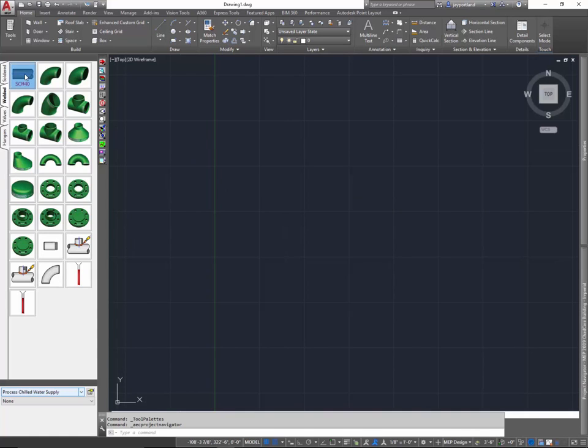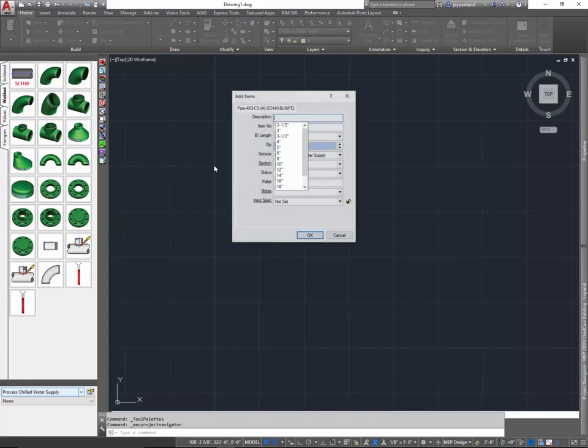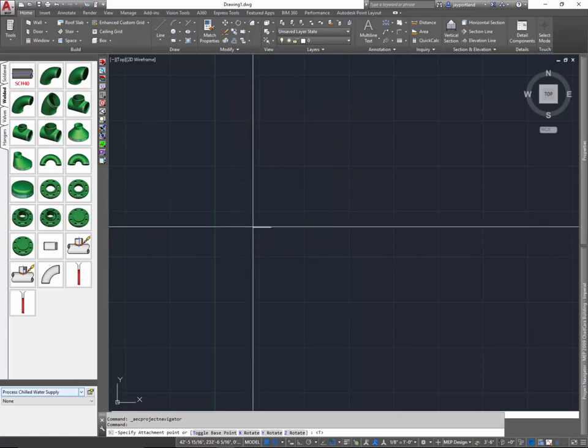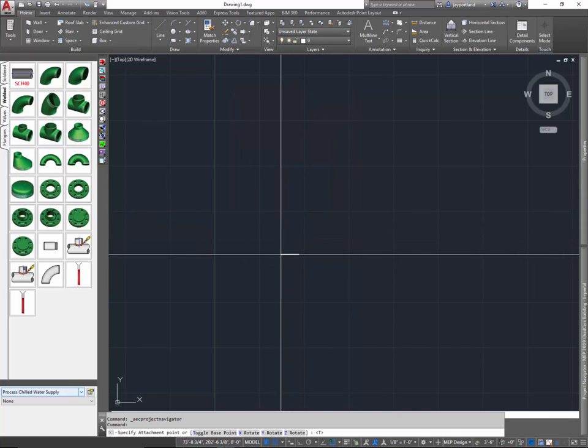If I select a pipe, I'll get a drop down here that says, hey Jay, what size do you want? So I want 6-inch, and by default, the 6-inch has a length that's associated to this. According to the service, they're going to be 20-foot sticks of 6-inch piping. Now, by default, you can change that so it's 10 foot or whatever distance you need. But by default, that's what's coming in, so I'll go ahead and use that.